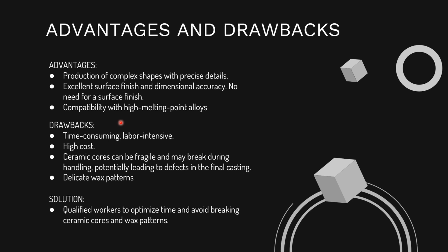However, some drawbacks are that it is very time consuming. As you saw, there are many steps, and it's also labor intensive, which means that we need to have people performing the task and people who are qualified. It is also high cost, and both ceramic cores and wax patterns are delicate and fragile and may break during their operation while handling them.